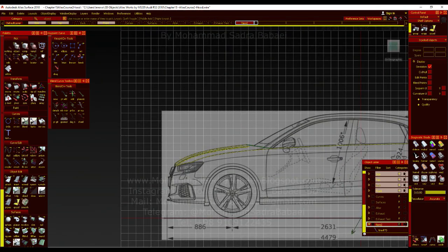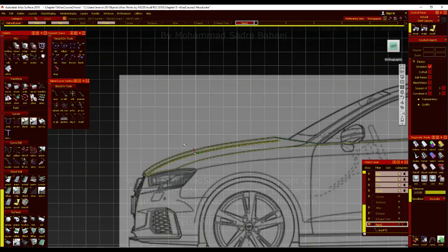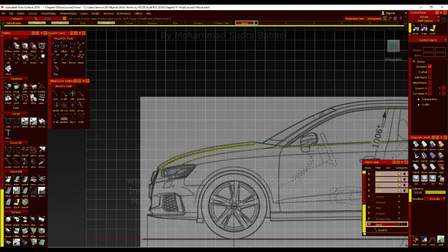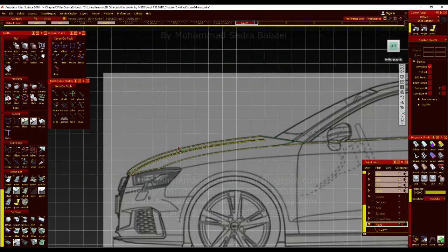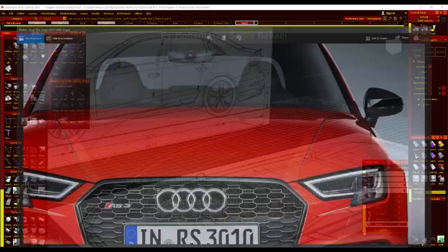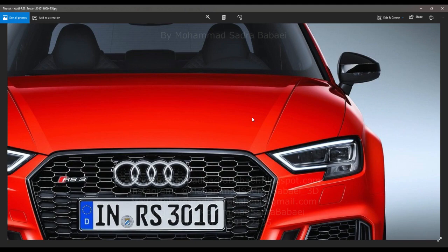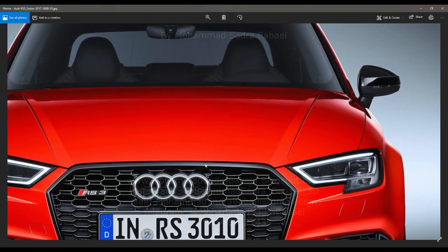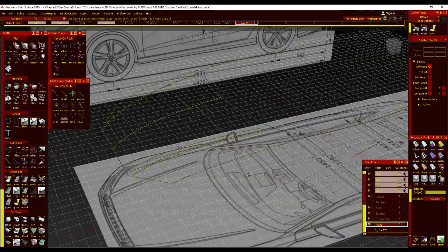So as we talked about earlier, we said that you should set the lines on a blueprint, on a side view, and for example one other view, front view or top view. I've just done that with the side and top. So we have some lines here as you see, and we have a soft surface here, another surface here with a positional connection with a little fillet, and another one here and another here.